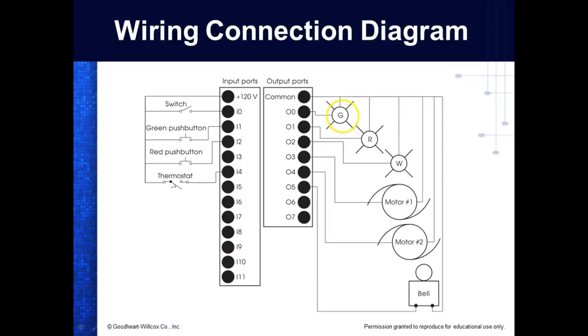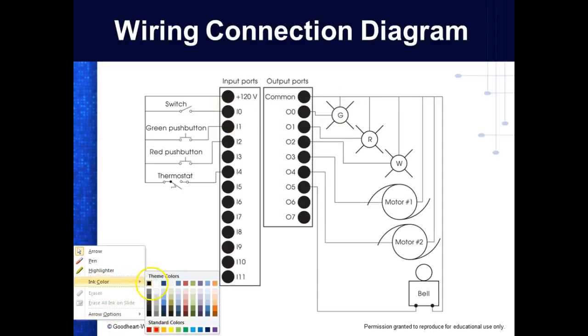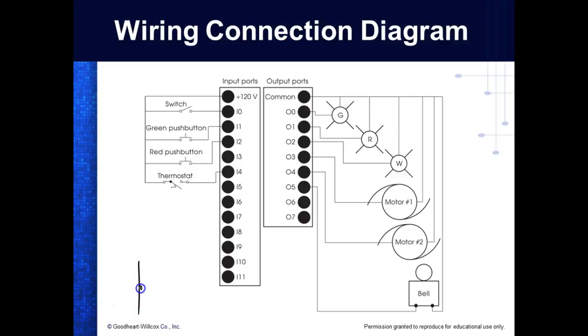But let's say this input is turning that light on. So my PLC program would look like this. Okay. And then I'd come over here and do that. And then I'd come over here and I'd draw a coil symbol. Or the OT, it's actually the OTE symbol, right? Sinking, it depends on what you hook to, what your input device is.